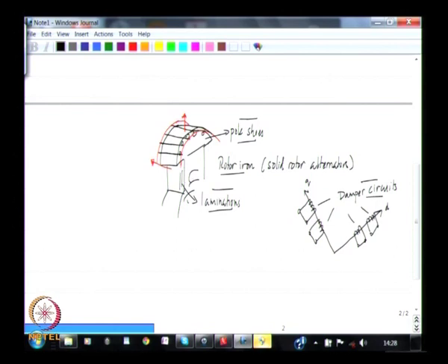All together then produce a field which then tends to retard against the oscillations of the rotor. So depending on the accuracy that one wants, one may go in either for single coil representation, one on each axis, or you may go for two coil representations on each axis and so on.